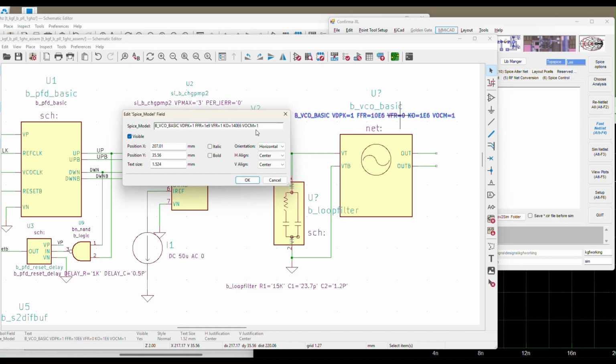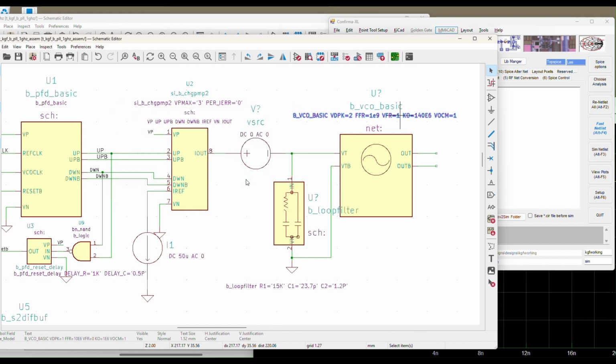I think this is okay. The common mode, I think we can work with that. So that should do it, I believe. If it doesn't, we'll come back and fix it if there's a problem. Maybe what I'll do is make the peak a little higher. So this is the peak, the sinusoidal peak, the differential peak. So I'm going to set that to 2. So I think each side should have a peak of 1 volt when you make that selection.